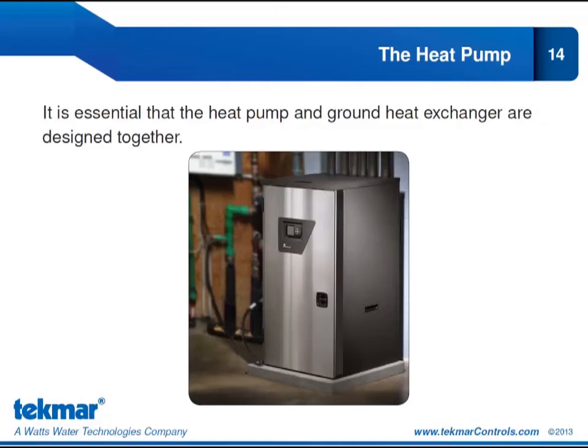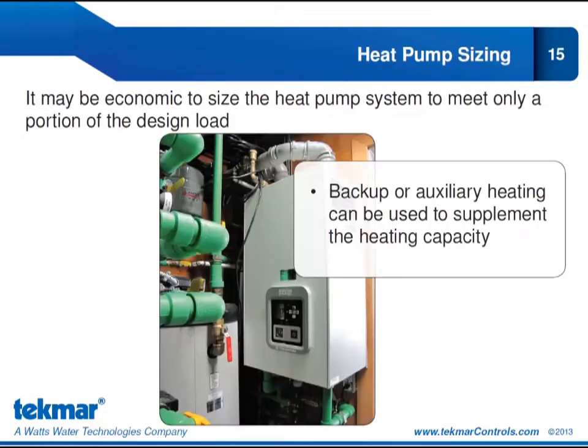Now, those typical entering water temperatures can have a lot of range. As we've just discussed, it depends on the location of the installation, the ground heat exchanger configuration, the soil or rock type, and the economics of the installation. All of these factors place practical limits on the highest entering water temperature that we can design for. And that has to be considered carefully when we are selecting the appropriate heat pump.